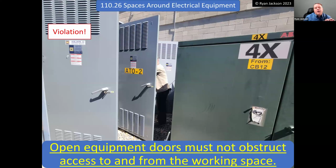Open equipment doors must not obstruct access to and from the working space. All right, well, I think on paper, this rule makes a lot of sense and it provides for a lot of safety. In that piece of equipment right there, normally what happens is when you open those doors, these little pins drop down in the bottom of the doors and they lock them in place at a 90-degree angle. So maybe you've got 4 feet between the front of that equipment and whatever it is that's behind you, a masonry wall or something, right? You got 4 feet, plenty of space. Well, what if those doors are 3 feet and they lock in place when they're open?